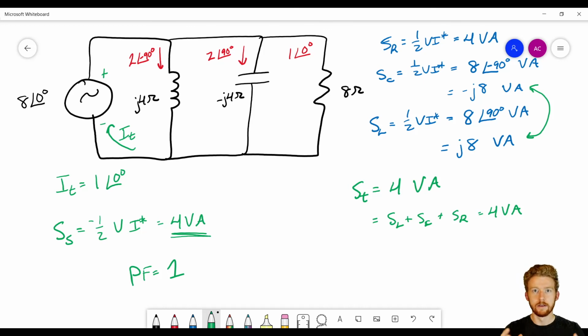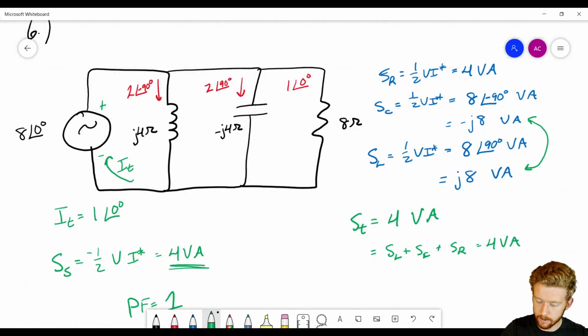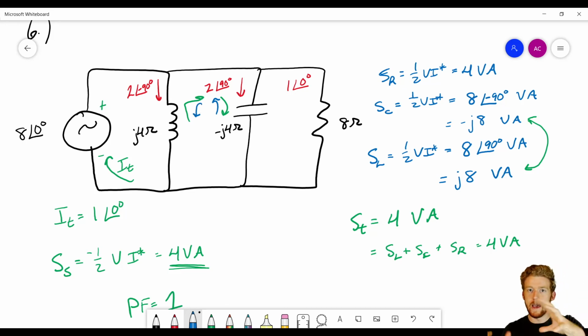So whenever the capacitor is releasing that power, the inductor is just consuming that same amount of power. And then whenever the inductor is ready to release it, the capacitor is ready to consume it. So they sort of just feed it back into each other. So if you look at this circuit here, there's power going here, and then after a little bit, it's going to flip backwards. Okay, so that power is just going back and forth. It's like that capacitor and inductor isn't even there.